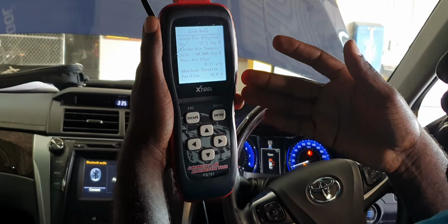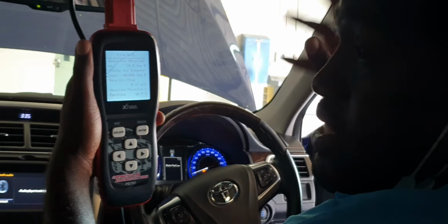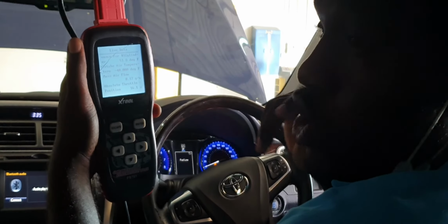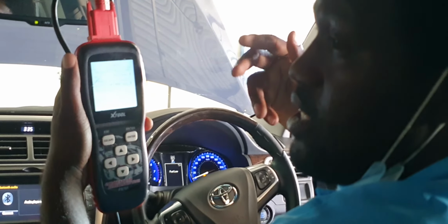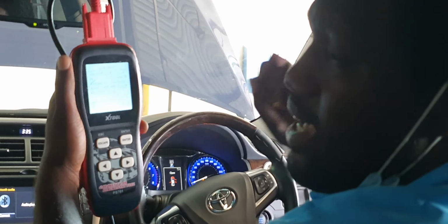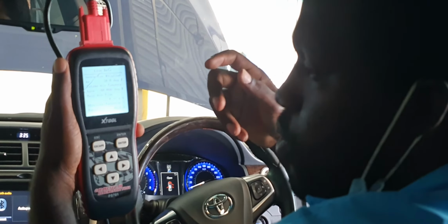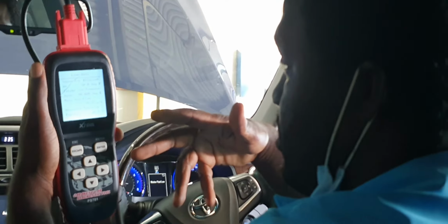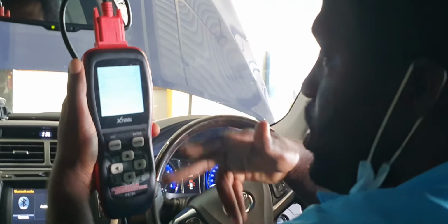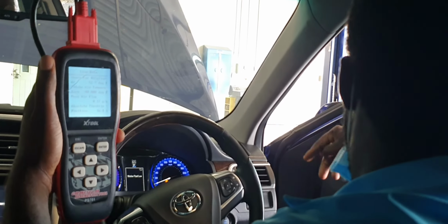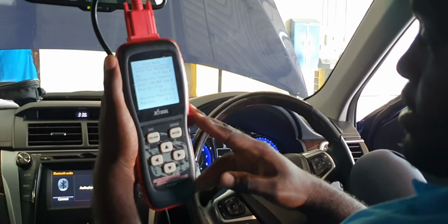So what this is showing us is that there is no signal coming from the sensor. But based on the diagram that I showed you earlier, if there's no signal coming from the sensor, it means that we would have to use our multimeter now and test the connector for the voltage that is coming out of the car ECU or the powertrain ECU to verify this. But since we just disconnected it for demonstration purposes, we can just connect it back. So connect back the airflow meter for me, please. When we connect it back, we will see the big difference.